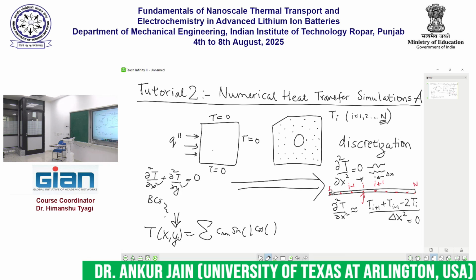In order to find out the temperatures at all of these nodes, I need to be able to write n equations. If I can write n linear algebraic equations, then I can solve those equations and find out what those n temperatures are, right? In fact, the problem of solving n equations in n unknowns is a very standard problem in applied mathematics, right? We write it in the matrix form.